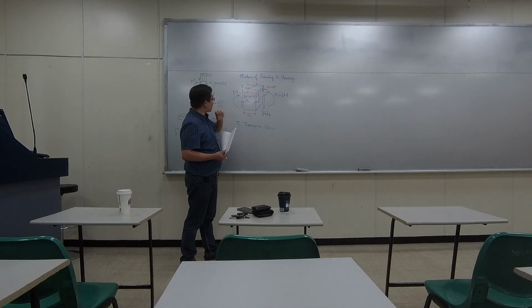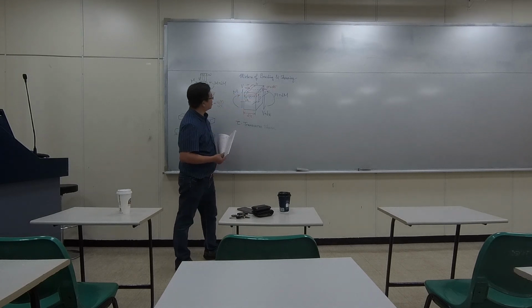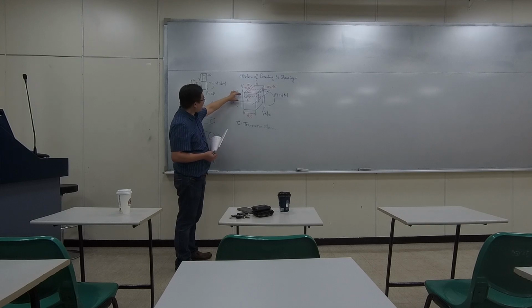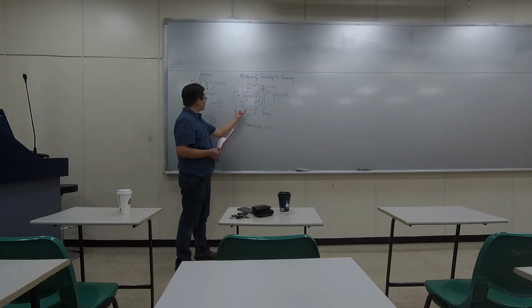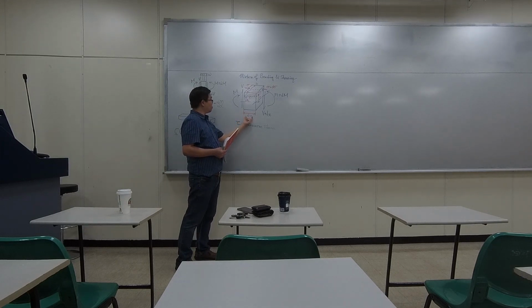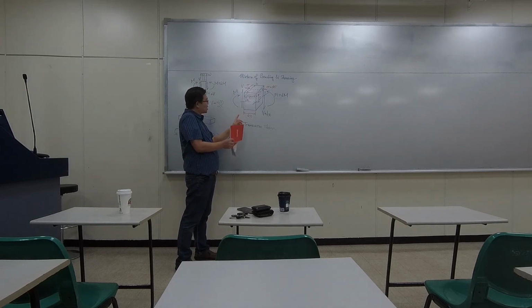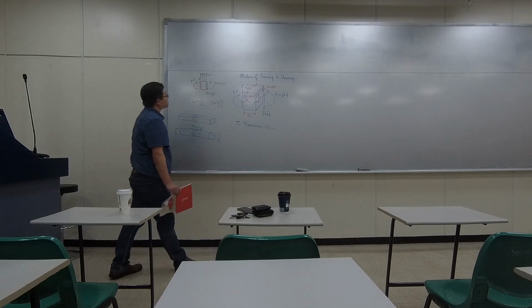And also we made a cut, a green one. The height of the cut is at a distance of Y1 from its plane to the neutral plane, the neutral axis. And the horizontal distance is very small. It's a small cut, so the width is dx.